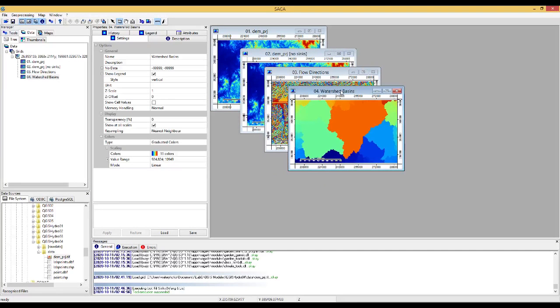As this tool processed the data, this tool also has basin functions. It uses the flow direction grid to find all sets of connected cells that belong to the same drainage basin and assigns a unique number to all the cells within that basin.